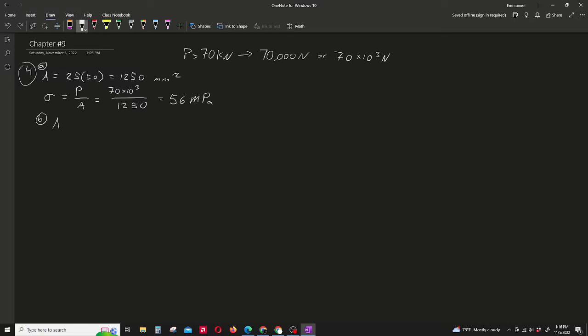The area for that is going to be the 0.7854, the pi over 4 times d squared, because they're saying that this is a 150 millimeter diameter wood post. And so the area for that is going to be 0.7854 times 150 to the second power. And after we calculate that up, we get 17.68 times 10 to the negative third meters squared in this case.